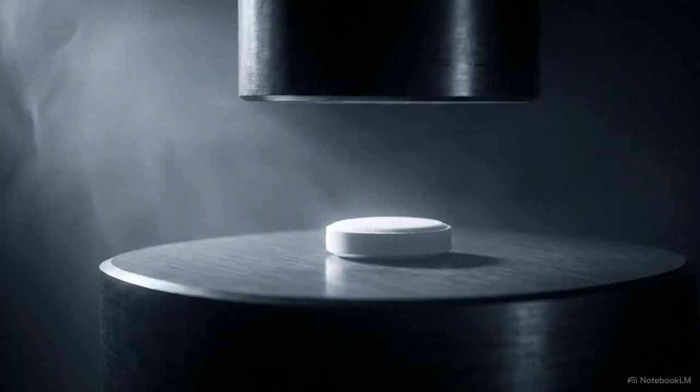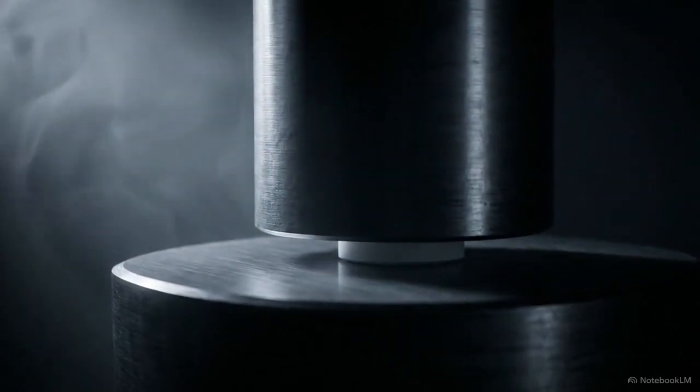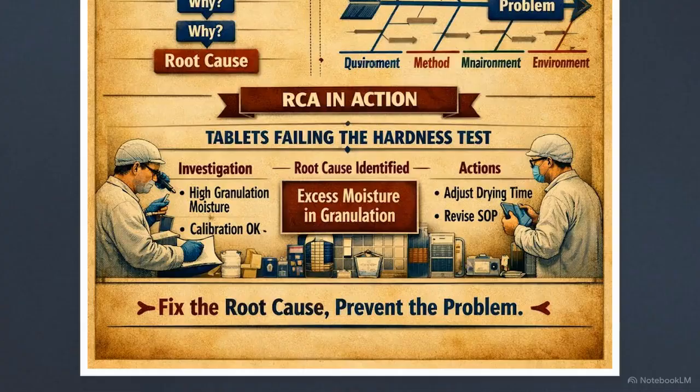Let's apply this to a real scenario. A batch of pharmaceutical tablets inexplicably fails the routine physical hardness test, shattering into powder under pressure. Our investigation log reveals the first step, verifying the machine's calibration. With that cleared, data points to the true root cause: excess granulation moisture. The team implements an immediate corrective action by adjusting drying time, then secures the process permanently by revising the SOP.